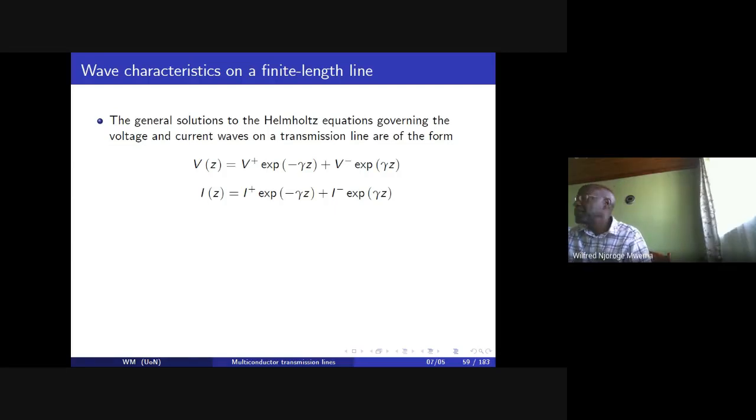Compared to the wavelength of the signal, you can see that when a power signal is being generated from Kitevu, it hardly even completes a cycle to get to Malaba, so to speak. This is what we are talking about, distributed circuits. And therefore, when we say that a circuit is small, we shall be using the electrical lengths rather than the actual lengths of the wires themselves. And the electrical length is the length of the wire in relation to the wavelength of the signal that is propagating on that wire.